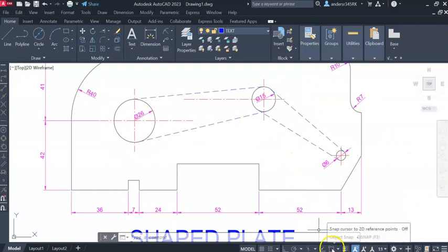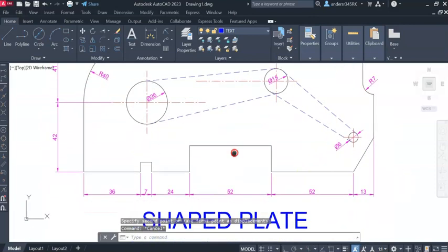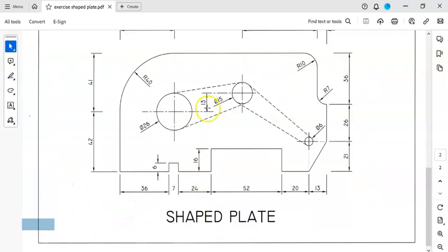I'm going to right click on there, and I'm going to make nearest my option there, and uncheck that. When it finds something nearest, it'll give a little dot like that, and we'll draw that in. So when I use the dimension option nearest, I don't want that line, all I want is the line between two existing lines. I'm going to use the nearest option.